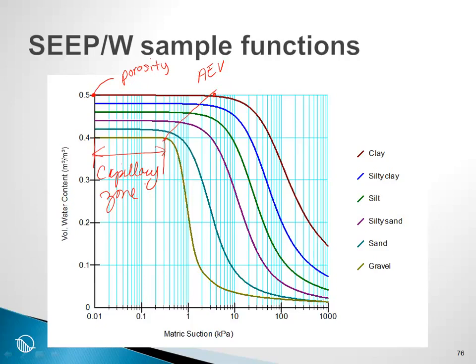My point is that determining this second point on the curve can be related to your general understanding of soil behavior and your field observation. The third point is that the residual water content is not that clearly defined sometimes, but even if you were to make that the phi residual approximately 10% of the saturated water content, it's not an unrealistic estimate.